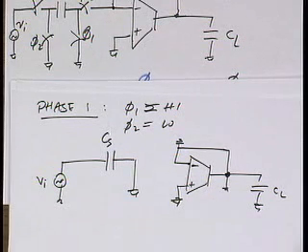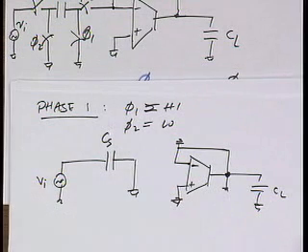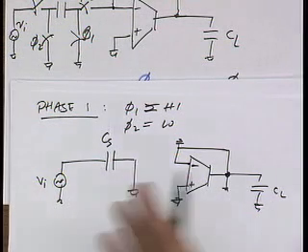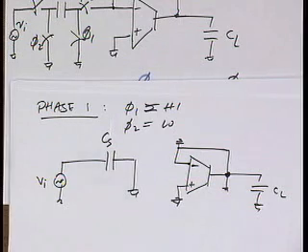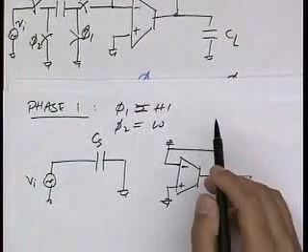Well, this is an OTA. An OTA doesn't have a buffer, and so if you put a short, what happens? Nothing special happens, right? It's a current source output. So if you short a current source, all the current goes into the output. That's fine, but nothing bad happens, okay? So sure, this is perfectly fine.